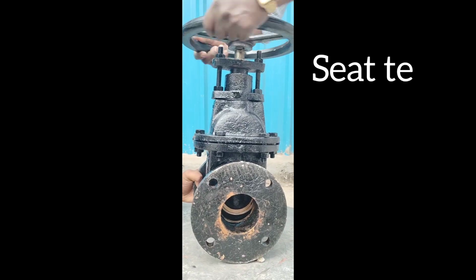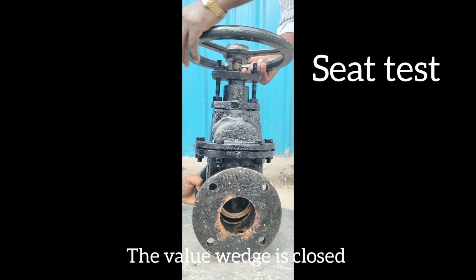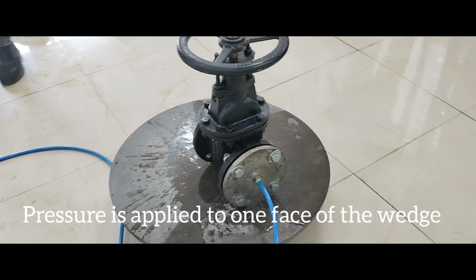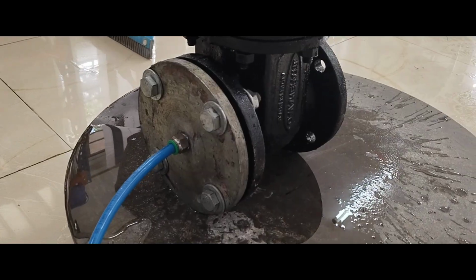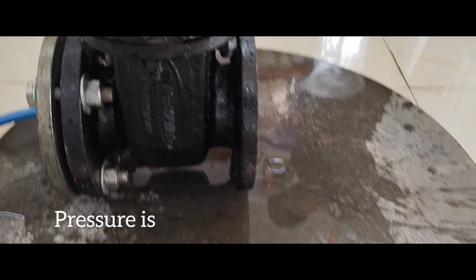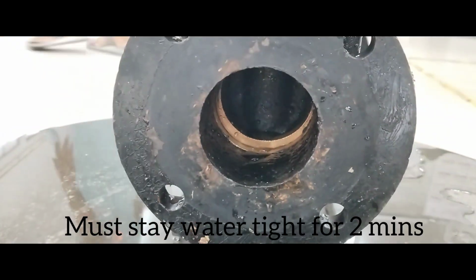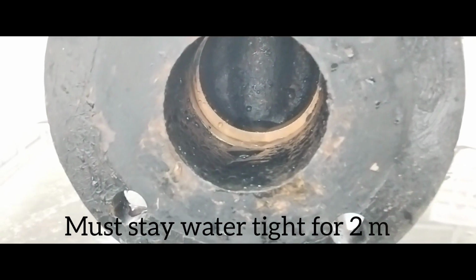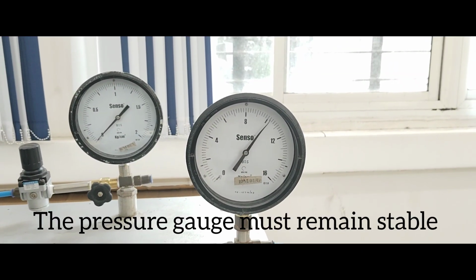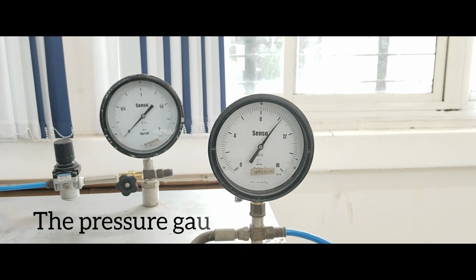In the seat test, valve wedge is closed and the pressure is applied to the one face of the wedge in the second test. Then the pressure is applied to the opposite face in the third test. The valve must stay watertight for 2 minutes and the pressure gauge must remain stable throughout the test.